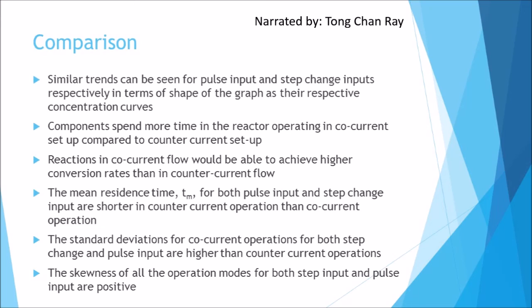Last but not least, the skewness of all the operation modes for both step input and pulse input are positive, meaning that the mass of the distributions is concentrated to the right. This can be seen in all the graphs in the figures shown previously, where there are right tails for pulse input as well as the bulk of the RTD concentrated on the right side of the graph in step input.